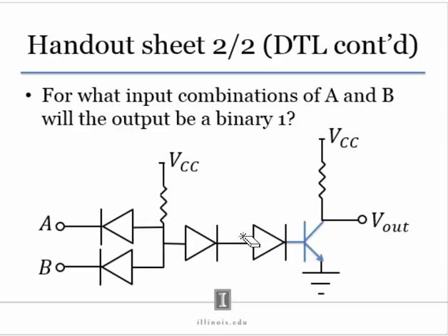All right, so the reason why we need to have this diode in the middle, and it's slightly a bit more of an advanced subject, is that you have to remember that 0 input can be as high as 1 volt, right? So we can look at this situation that we indeed have a high 0 here, 1 volt, and 1 volt here. And with this being 5 volts, we're still going to turn on both of these diodes, A and B,